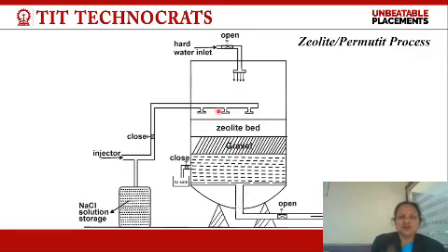It is the softening passage, and when the zeolite bed is exhausted, how can we understand that the bed is exhausted? When all the sodium ions present in zeolite are exchanged for calcium and magnesium, then the zeolite bed is exhausted. And at that condition, we should regenerate or wash the zeolite bed for the further process.